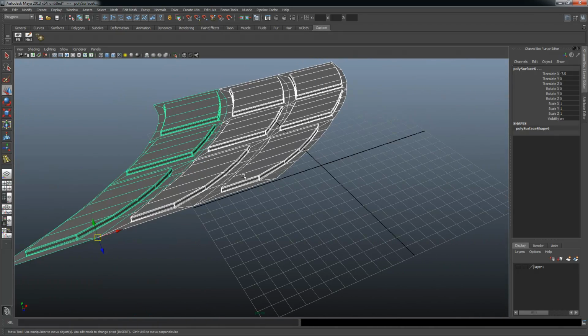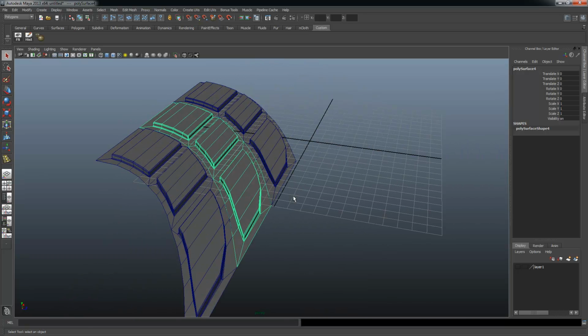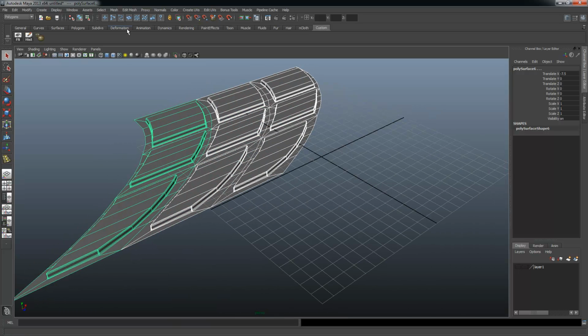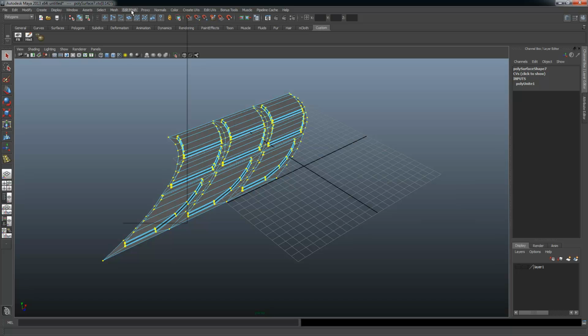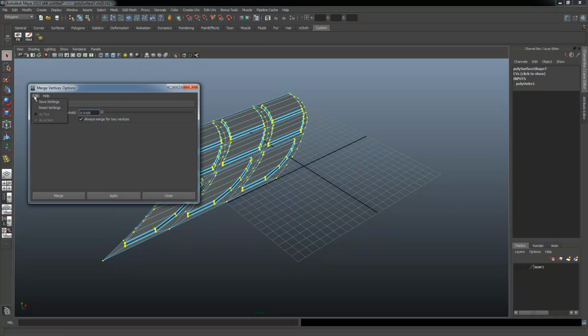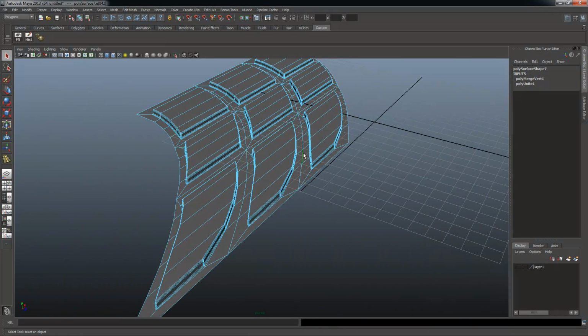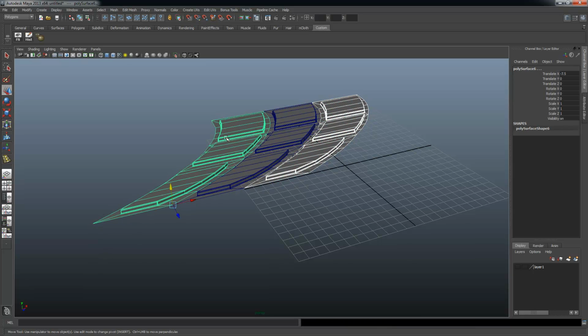And so what this means is that I can now create multiple copies of this one tread, forward or backward, and they're going to line up perfectly. All I need to do in order to merge them is first go to Mesh, Combine, go to Vertex Mode here, select the entire thing, and then say Edit Mesh, Merge. I can use my default settings here, which is a very low threshold, 0.01, which basically means, hey, if these verts are right on top of each other, they're going to weld. And then when I do that, there we go, the whole thing's welded, and I can demonstrate that by selecting one of the edges and pulling them up, and you can see here that it's connected. So I've made my life very easy by doing that.